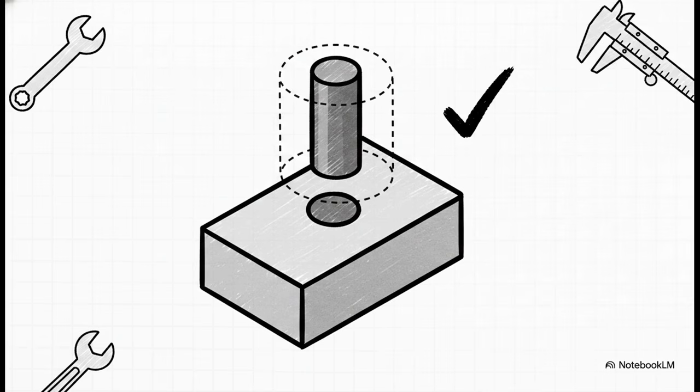This also completely explains why parts toleranced at RFS, regardless of feature size, cannot be checked using these same fixed gauges, because RFS doesn't give you any bonus tolerance. Its boundary isn't constant. It shrinks and grows depending on the produced size of the feature, meaning a single fixed size physical gauge pin just won't work.